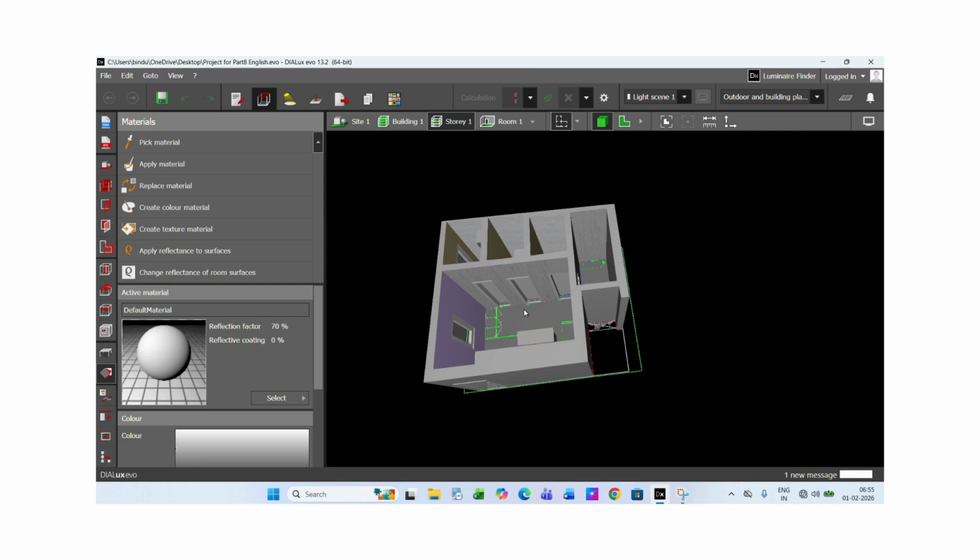Or suppose it's an office, and you have an office table where you are keeping your files and reading and writing. This is on the table, so the table becomes the working plane. Normally the table will be 0.8 or 0.9 meters high. That is the average height, so you can treat the height of the working plane as 0.9 or 0.8, whatever you want.